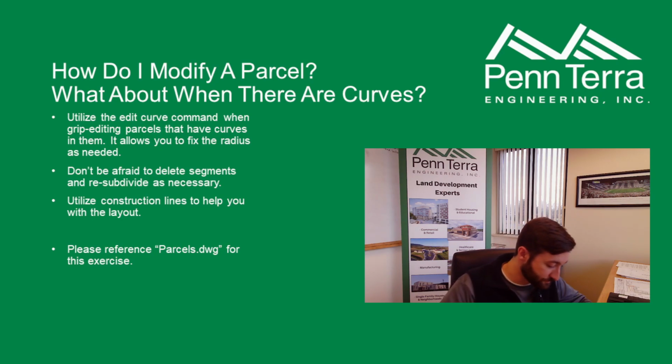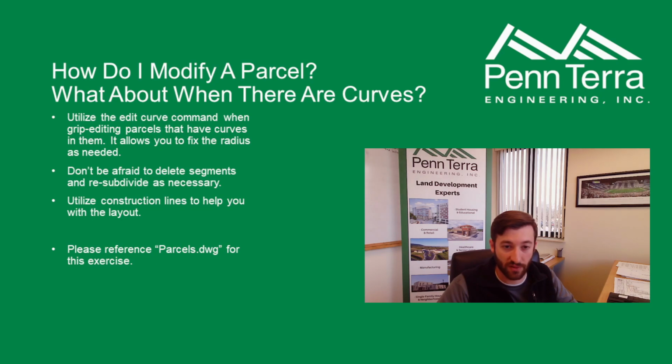Okay, so how do I modify a parcel? What about when there are curves? One of the complaints that I always hear people have when they're dealing with parcels is they're a pain to modify. Someone said I need to move this lot line over a few feet. I try to do it and it messes everything up. What do I do, especially near a cul-de-sac when I have curves? So there are special commands you can use to take care of that. We're going to jump into the parcels file again, and we can run through some of that.